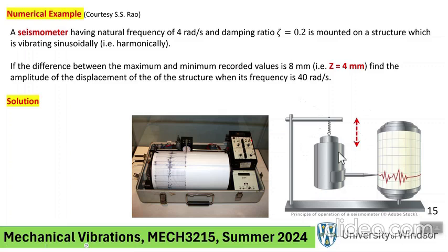On the other hand, the other end is accelerometer, where R is small, right? In general, look at the section of the graph, which was accelerometer region. R is small. If R is small, that means omega n is large. And once again, look at the formula for omega n.